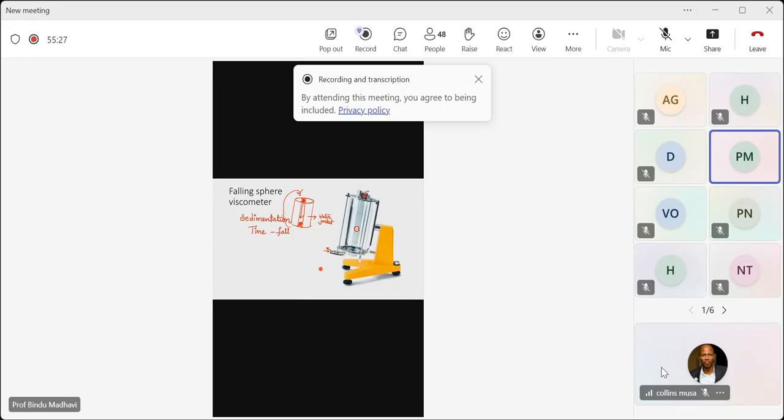So here we have some advantages. There is no influence of temperature. There is no need of using any reference liquid. It is direct measurement of the test liquid without comparing with any viscosity of reference or density of reference or the time taken by the reference. So that is the main advantage. You have a control over the temperature because of the water jacket that is present, but you do have certain